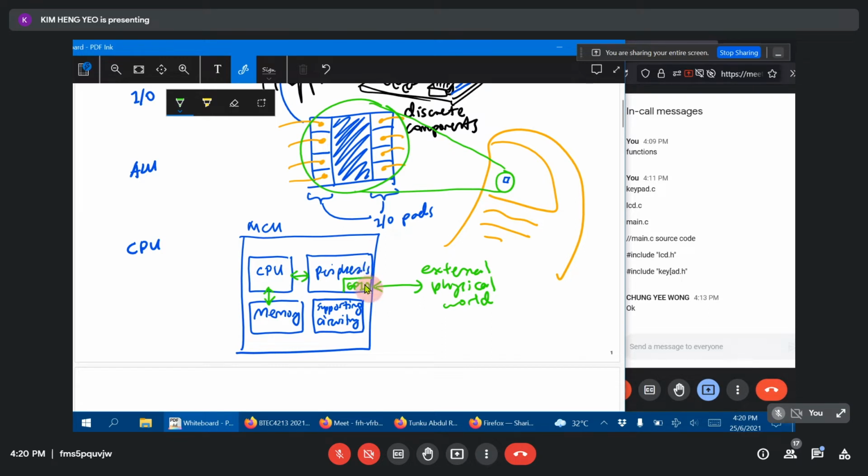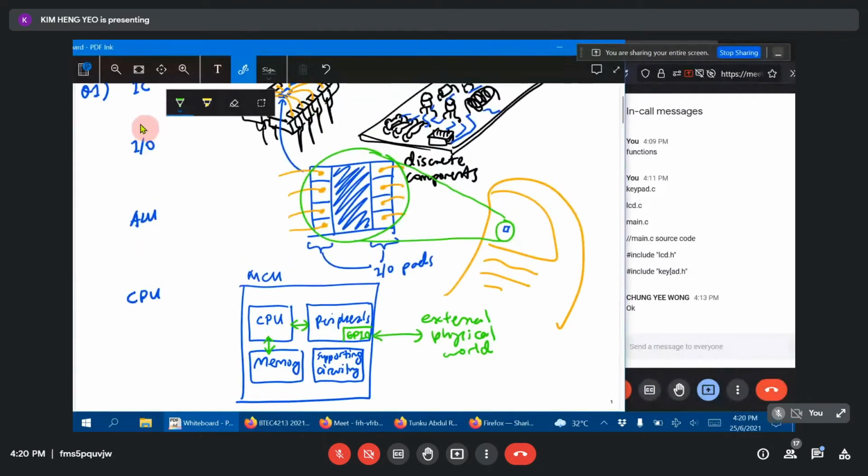Those are other types of I/O ports. But the most basic one is GPIO. Okay, and GPIO is your general-purpose input output. The reason is because your processor does not have sufficient voltage or current to control external devices. The processor's signals are very low voltage and low current. So you need this special circuitry here, this GPIO circuit.